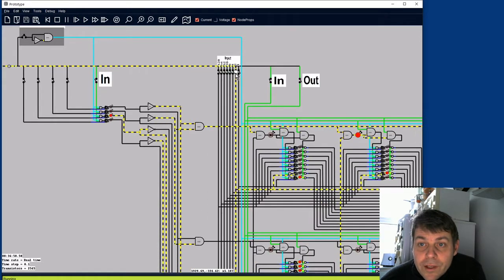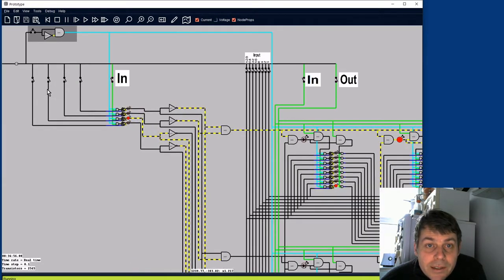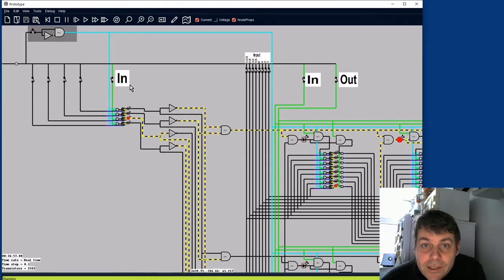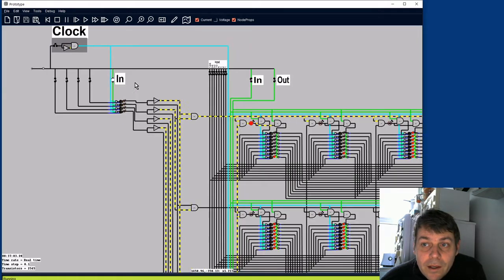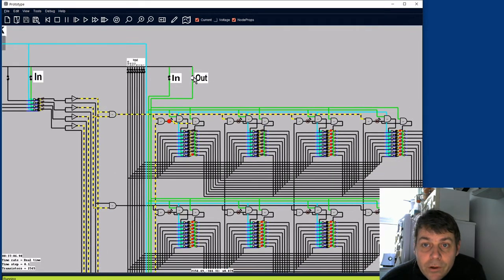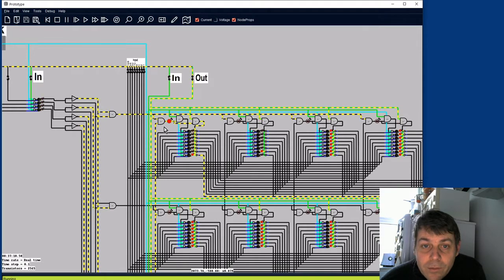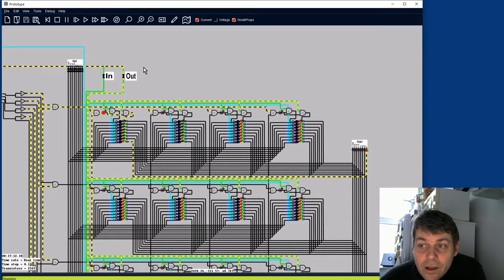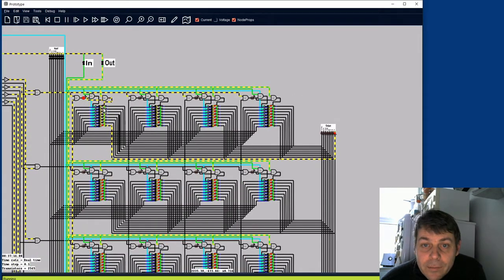Now if we switch off the input bus, I'll now put 0 back into the address register to readdress this cell. And if we now switch on the output, it doesn't require a clock pulse. It will just output whichever cell we have addressed. So that's the 1 value that we put into this upper left cell.